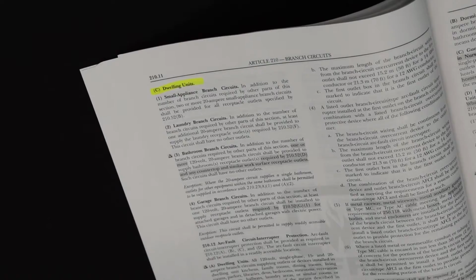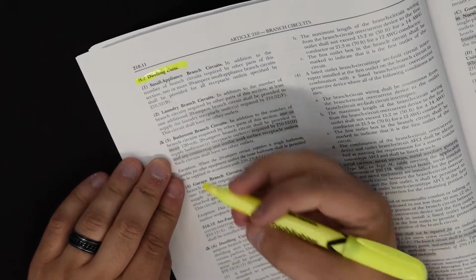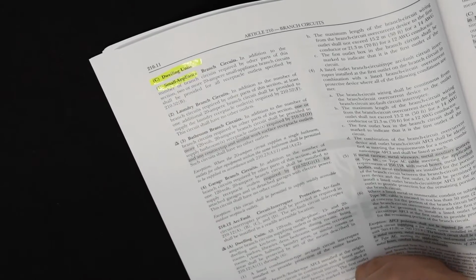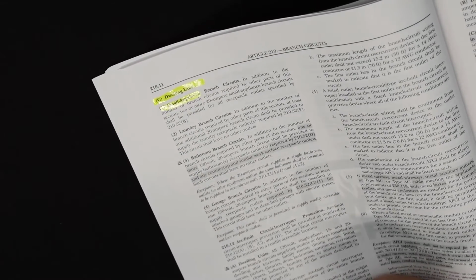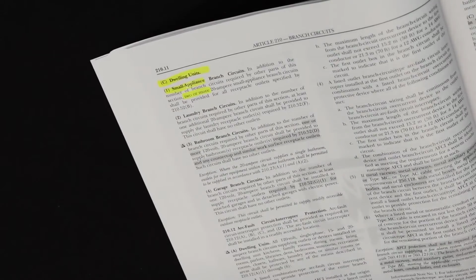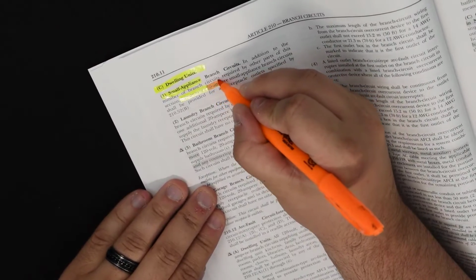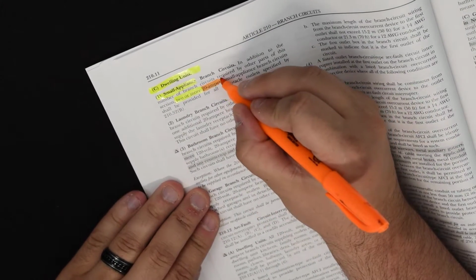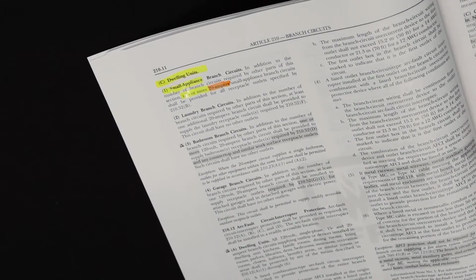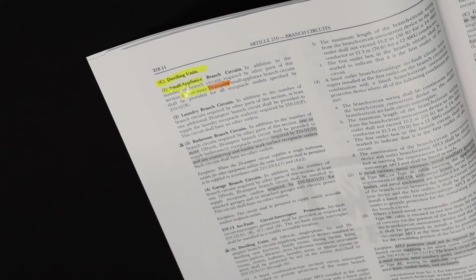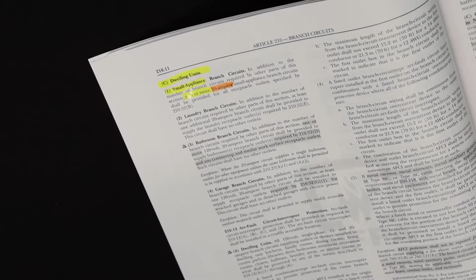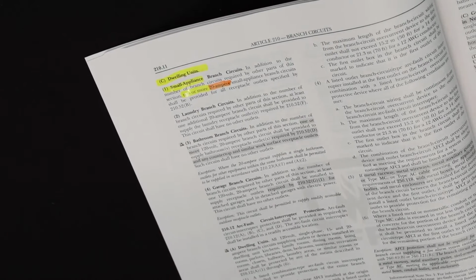And we've got 5 different pieces here. The first piece says small appliance branch circuits. So highlight small appliance. In addition to the number of branch circuits required by other parts of this section, highlight 2. It says 2 or more, so highlight 2 or more. And then I take the dark color highlighter and highlight 20 amp. Shall be provided for all receptacle outlets specified by 210.52B. Now 210.52B, we're not going to go there, but that is the layout, how many receptacles you require based on a layout of the floor line in a dwelling unit.